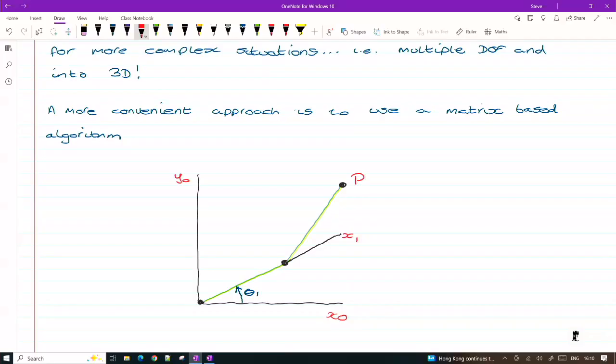So as this link moves, as this joint rotates, X will also move. It's fixed to the end of the link, okay? So it will move with the link, so that x-axis will always be collinear with that link. And that means our y-axis is, anybody want to give a guess? Okay, so that's our y-axis. Call that y1.